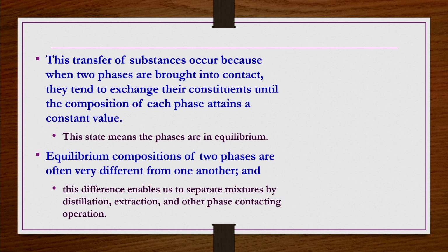Let us say you have a methanol water system, and what the equilibrium curve of this system looks like depends on that. You can decide at a given temperature and pressure whether the separation of a methanol water mixture into almost pure methanol and almost pure water as separate phases is possible or not. Those things one can understand.